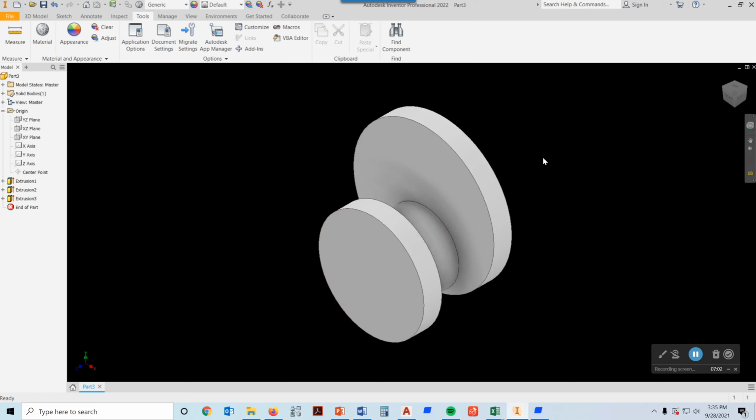And when you make the drawing for this, you can make sure that it says ANSI, A-N-S-I, and then mm for millimeters, if you want to check that same way by going to Tools and Document Settings when you get into your IDW in the drawing for this.